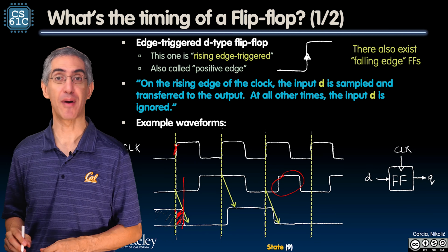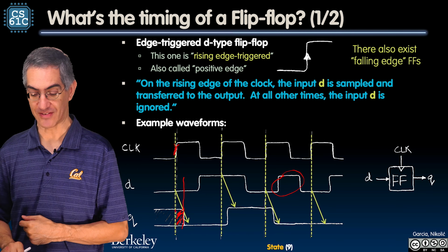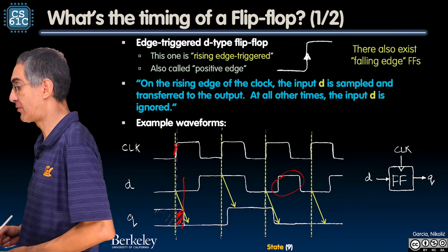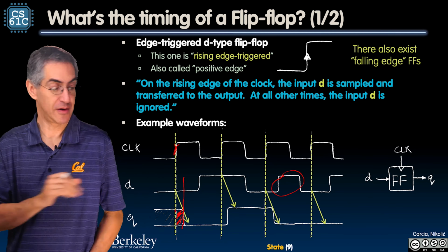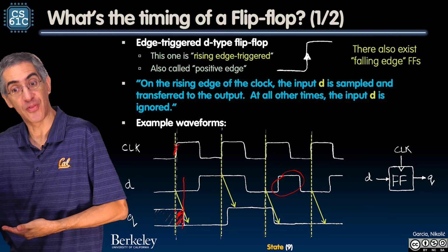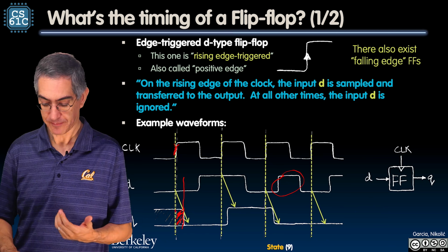But from the point of view of the flip-flop, I don't care, because last time I sampled it, and now I stay the same. So nothing, from my point of view, I grab it, 0, turn around, D's changing, 1, 0, 1, 0, turn around. If it's still 0, I just grab the 0 and give it again. But I mean, the output should not see it. It'll still be 0 throughout that whole period on the output side. Okay, so far?